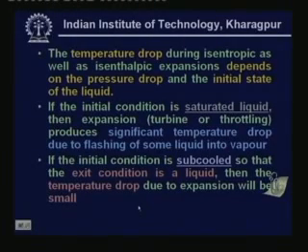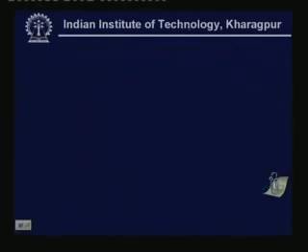Now we have considered the case where the initial condition is saturated liquid. Let us see what if the initial condition is not saturated but subcooled, so that the exit condition is liquid. Then we find that the temperature drop due to expansion is small. Again, let me explain this one.